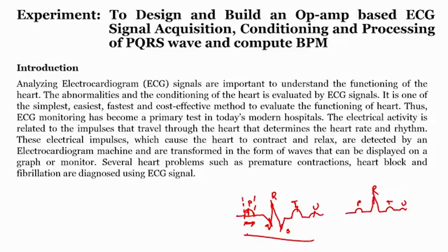So if I want to calculate only the peak of R, I have to understand how to differentiate between a peak and a point, right. When I do the digitization of the signal, we can take different samples at different intervals, right. But how do you decide this particular value is a peak? In order to do that, I have to compare the peak value with the next subsequent value as well as the preceding value. For example, say I take this particular value,